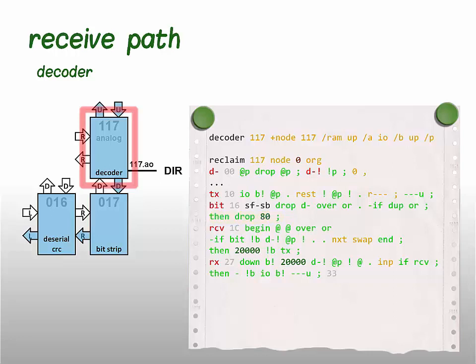The main word for receiving packets is Rx, which is called when we expect a packet from the device. It initializes variable D- to idle state of D- line, and then it calls word input in node 217 and fetches back a flag. If non-zero, we have a sync recognized, and we jump to word receive. Here we receive a pair of D- and D+ line states.